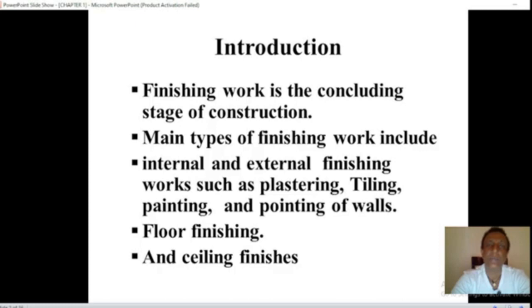The other chapter is pointing. Pointing is a method of repairing mortar joints to improve the appearance of stone or brick surfaces and to protect the wall from weathering actions. The joints on the surface of brick or stonework are filled with mortar evenly while the building is being constructed.